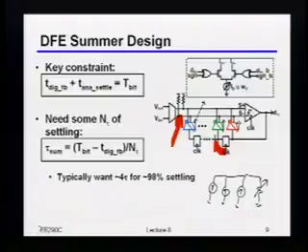And so that nonlinearity is worse than the GM of your preamplifier? It depends. It's not necessarily worse, because it really strongly depends on what the RO of those switches are and what their V star is compared to the V star of the input device. Exactly how big that nonlinearity is really strongly depends on the exact design you're doing. In practice, you can actually do a very large number of taps and not necessarily have it be too big of a problem, as long as it doesn't cause you to compress too heavily.